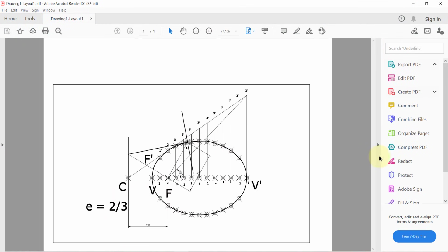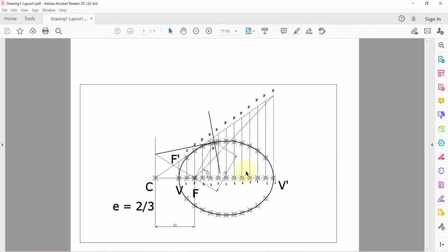So this is how you finish the ellipse by using general method in the 2007 version. Here everything is finished. If you want, you can even write the information of the value here, that is general method, construction of an ellipse. Question is this. If you observe carefully, the line weight is also shown here. So if you give more line weight, the line also will be a little dark here. So in that way you can give this. So that is about this question.